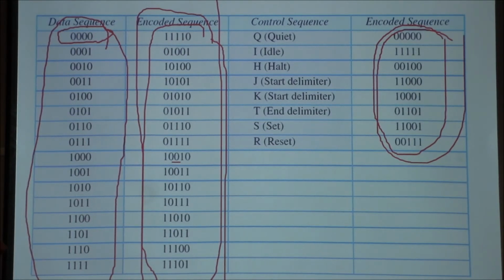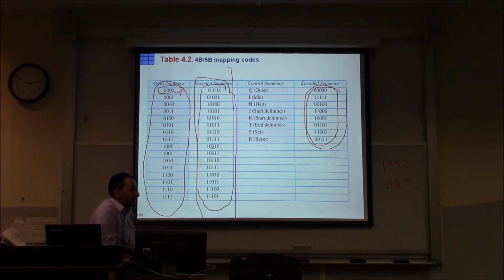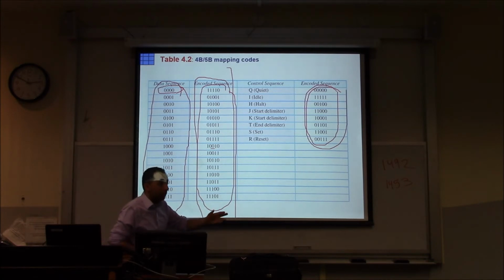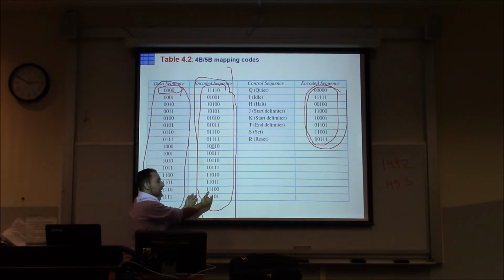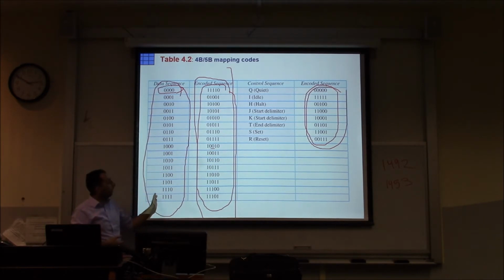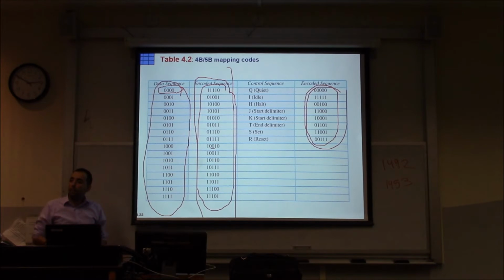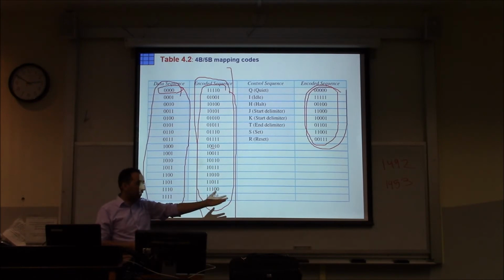Yes, you have a question? So, by adding the extra bit, you're doubling the amount of information. Excellent observation. Yes, that's what I said. We are adding more bits. That means if I want to send 8 bits using block coding, the 8 bits end up as what? 10 bits. So that leads to what? Decreasing the data rate that we have. And that is one of the disadvantages of block coding. Adding more bits makes the data communication efficiency less in this scenario, but we are compromising that for what? Adding synchronization, adding self-error detection. So those are the advantages of block coding.